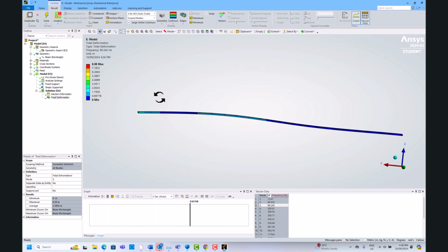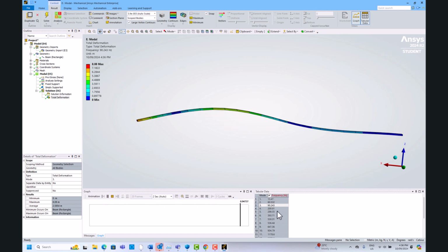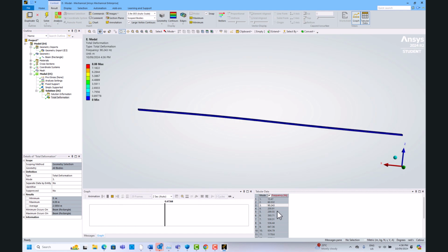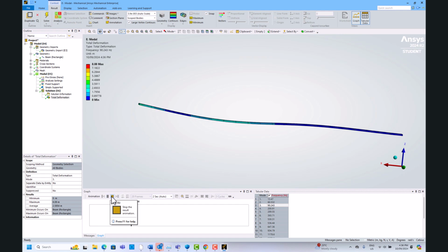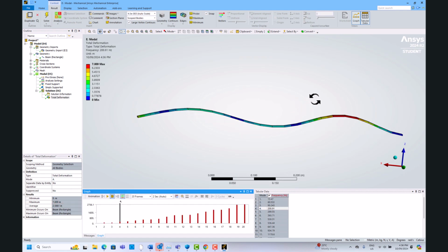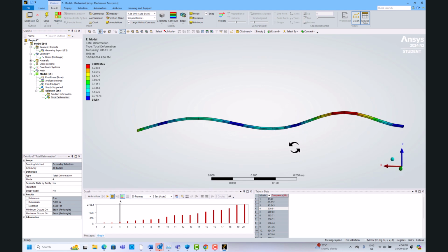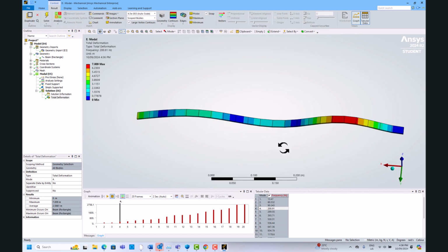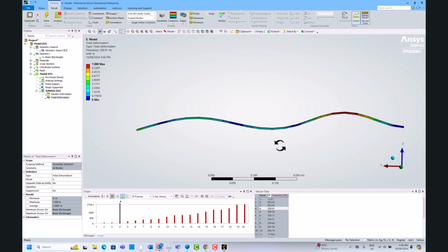The software package doesn't know what type of vibration this is. So they just put everything into one big table and give it to you. So you have to, like what we are doing, just look at each mode shape to identify, okay, this is the third mode of our vertical vibration.